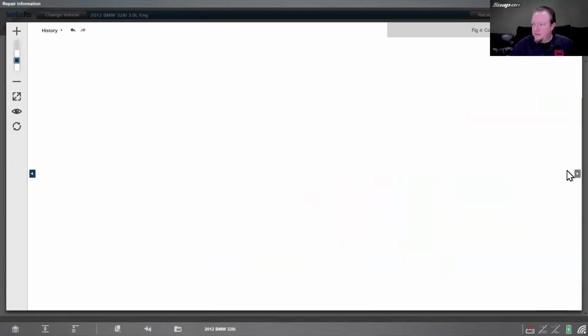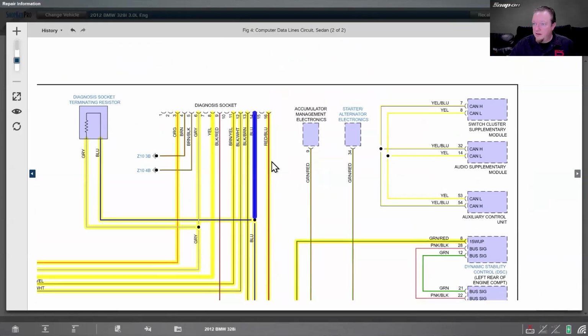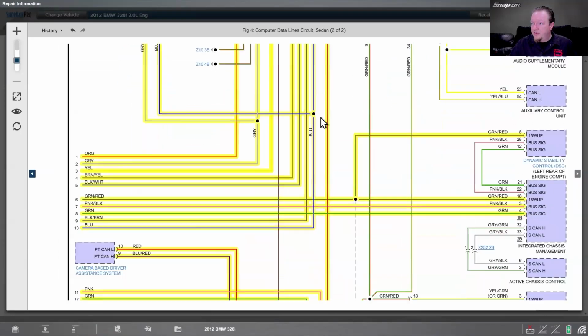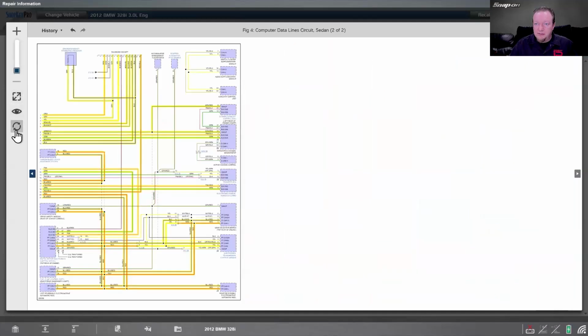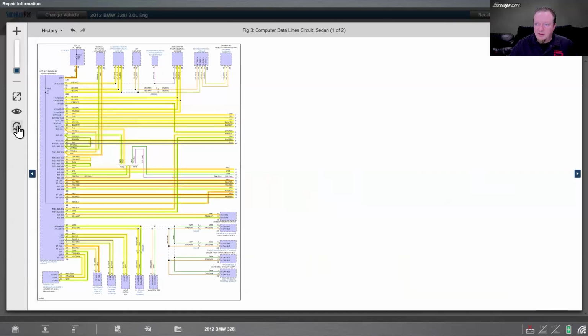And then if I go across the way, that's going to bring us to the, where is it? There it is, diagnostic connector right there, 16-pin. This one actually has a terminating resistor in there between 6 and 14 for the CAN bus. Interesting. You don't usually see that called out on many vehicles. This one also, if you notice, it has a couple splice connectors there, but it doesn't have any of those termination blocks that we looked at earlier. So this one's fairly straightforward.